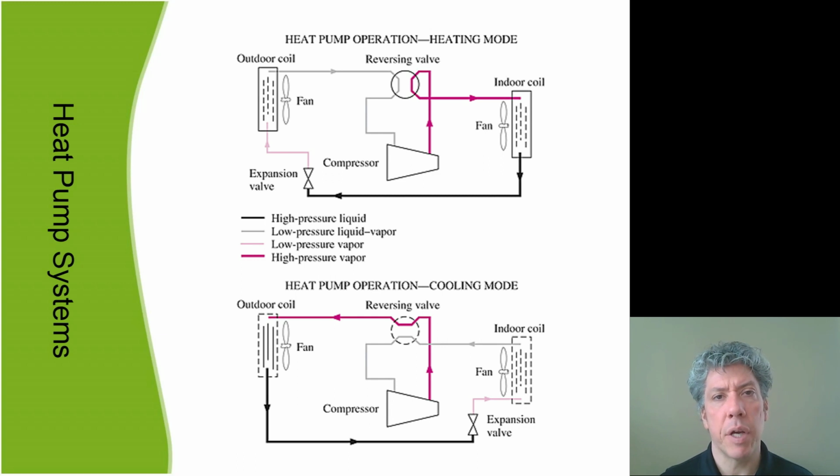And what happens there is the pressure of the refrigerant is dropped. So the liquid, usually 10 to 30% of the liquid, will boil off, and in the process cool the bulk of the refrigerant. So now the refrigerant's cold. Now typically you don't want the refrigerant to get down to freezing temperatures. The reason is because you then run the fairly cool refrigerant through the indoor coil, and if the refrigerant is at some temperature below the freezing point, any water in the air that's cycling through the unit will freeze, and so the coil will freeze up.